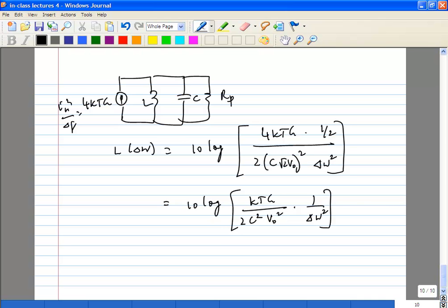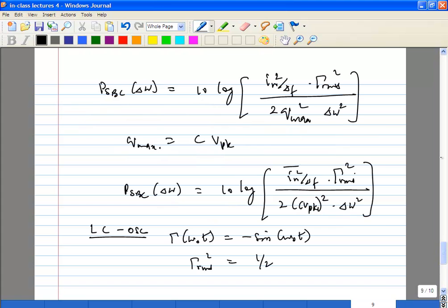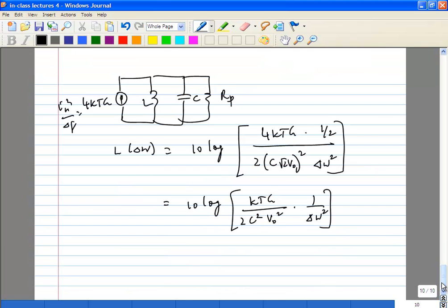We'll come to it. We are actually coming to it. We are going to consider that next, because right now we are just considering the impulse response, the output noise due to a white noise source. So remember that we assume that IN squared delta F is white in this case. Okay, we'll come to it next. We'll see what happens when you have just flicker noise.